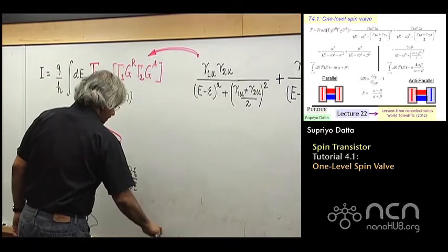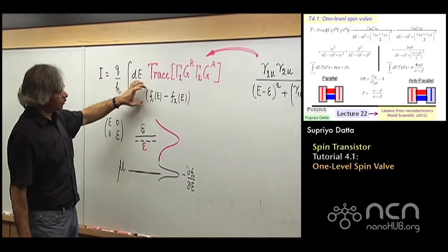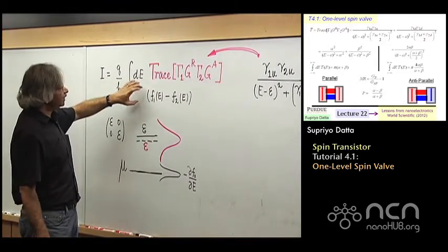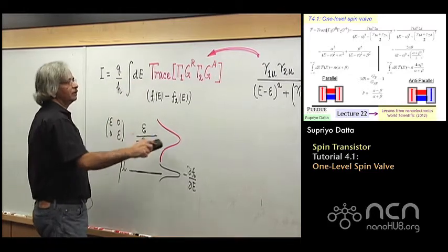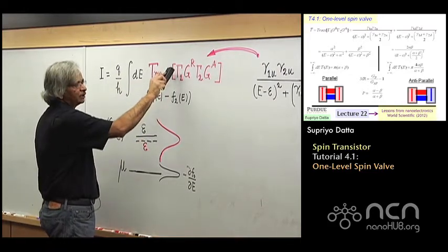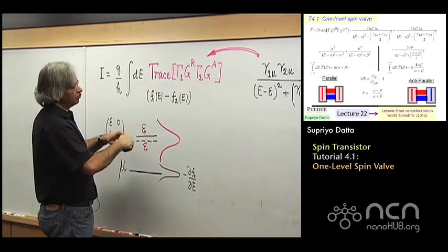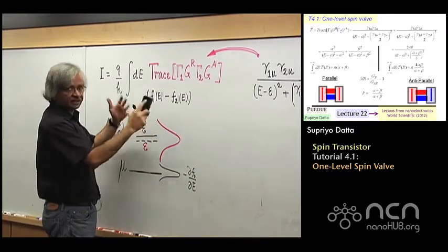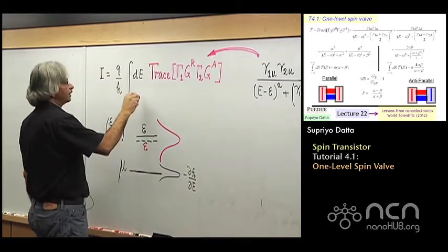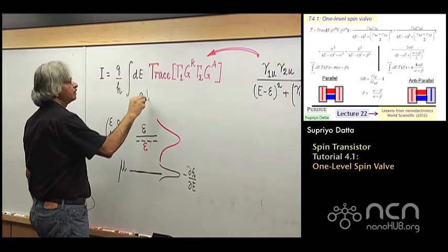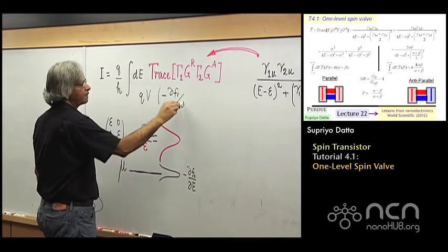Now, as we discussed earlier in part 1 again, when you actually calculate the current or the conductance, it depends on the value of this quantity around the Fermi energy. So what you do is, we use that linear response, this Taylor series expansion for F1 minus F2, and we wrote it as qV times minus dF0/dE.